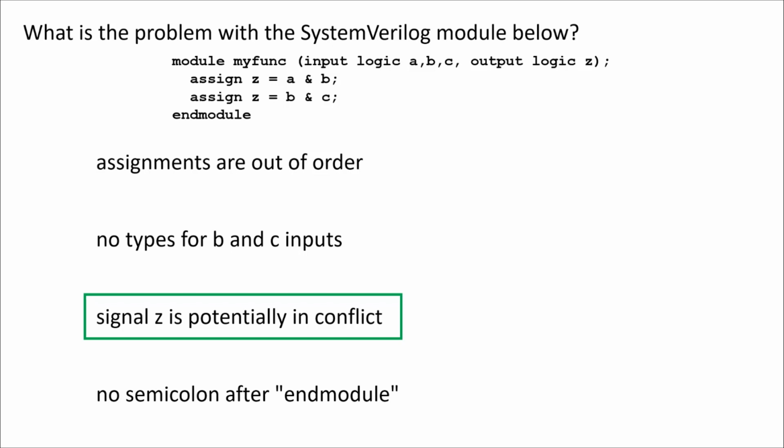So there are 4 states. Now, one thing I want to mention is there's a very popular compiler called Verilator. You might come across this. Verilator is a program that you can download on any Linux machine for free, and it will actually compile Verilog into an executable file. It's pretty cool. In fact, I was going to demo it in this class, but it has one horrible weakness. It only supports 0 and 1 for logic signals.